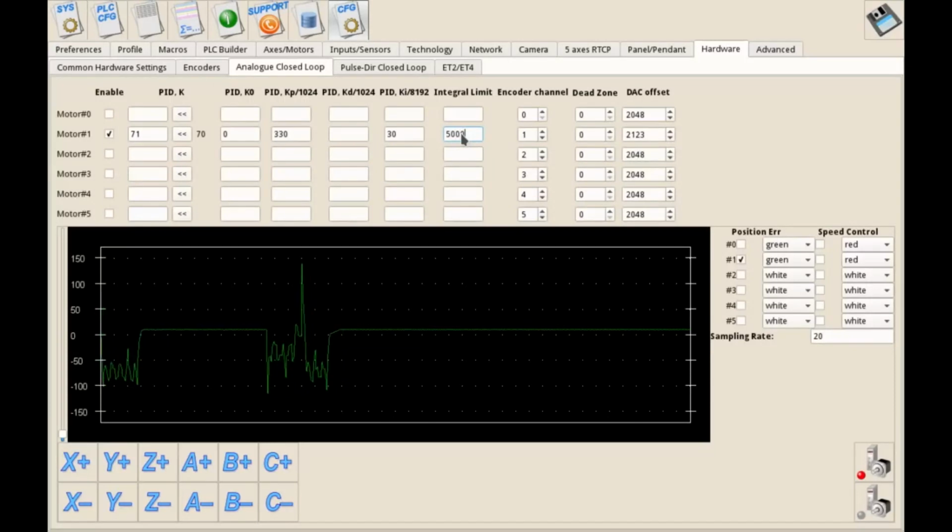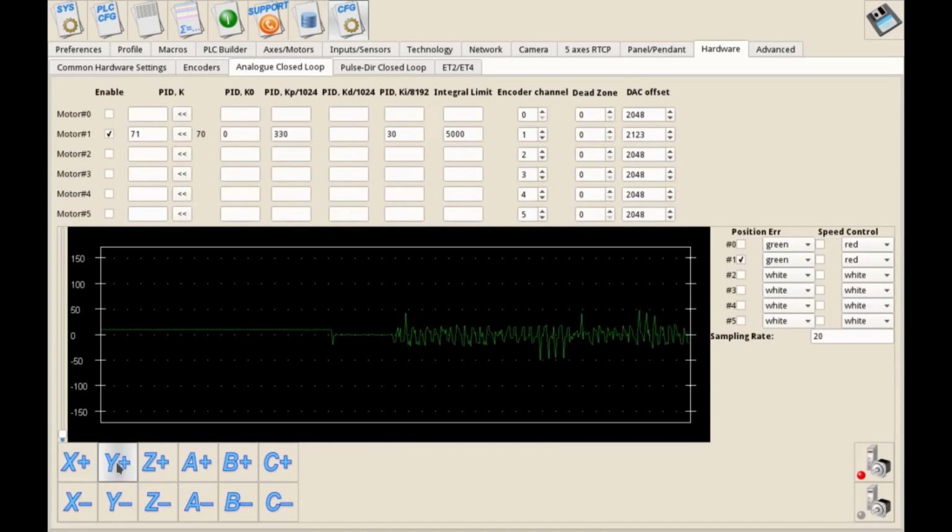Again, my servo drivers are more than 25 years old. They aren't very fine-tuned or anything like that. So you can see that the PID controller has to be set up on the real machine by the real user to effectively tune the values to the point where they need to be. And if we save this, the PID controller will be ready on the next run.